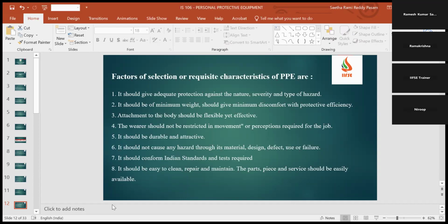Cotton gloves are not suitable for handling acids. Only neoprene or nitrile gloves should be used for acid handling. Okay, fine, to keep it simple, rubber gloves, because these are all different types of rubber. If I use leather gloves for handling general housekeeping materials, definitely it will help, but it will give discomfort to the worker. For acids, PVC gloves are also suitable.